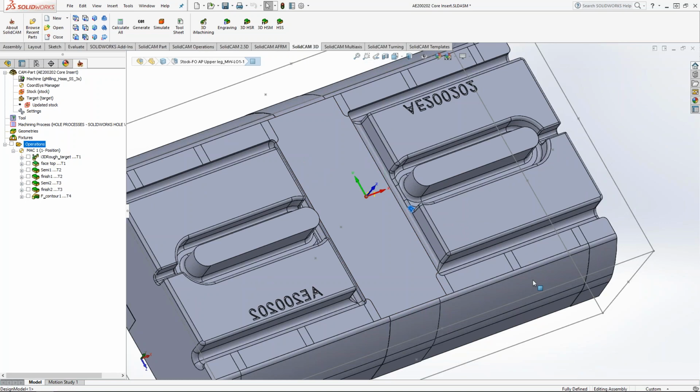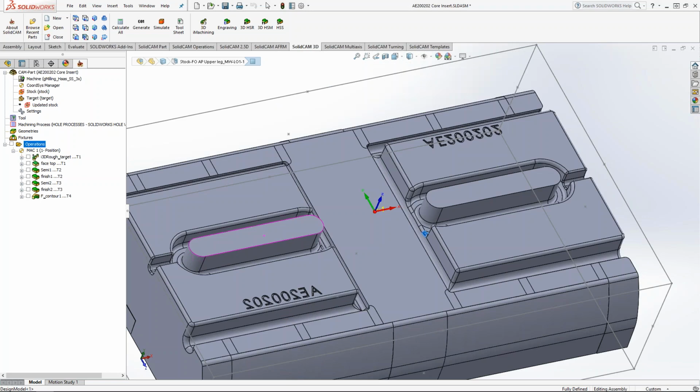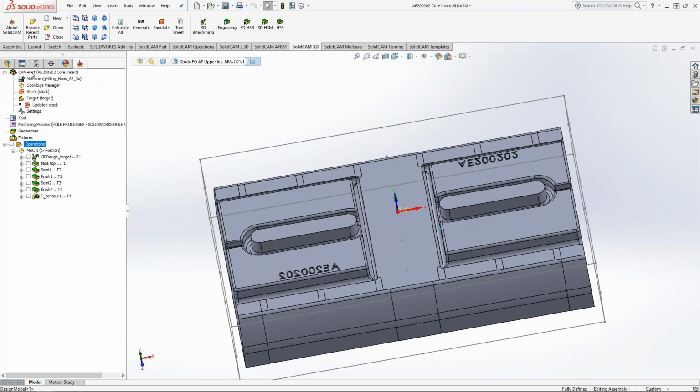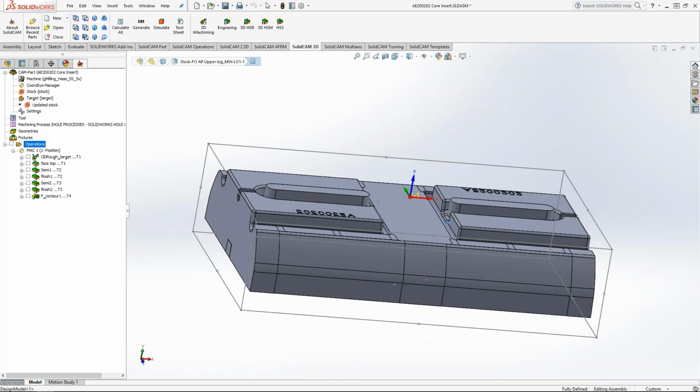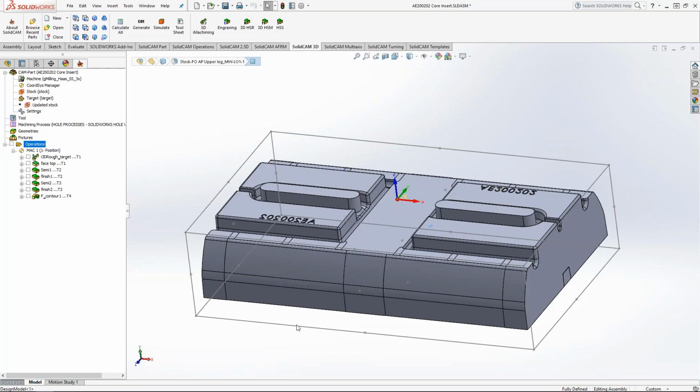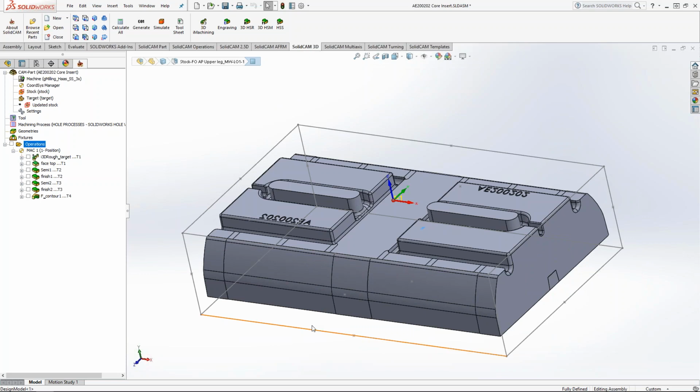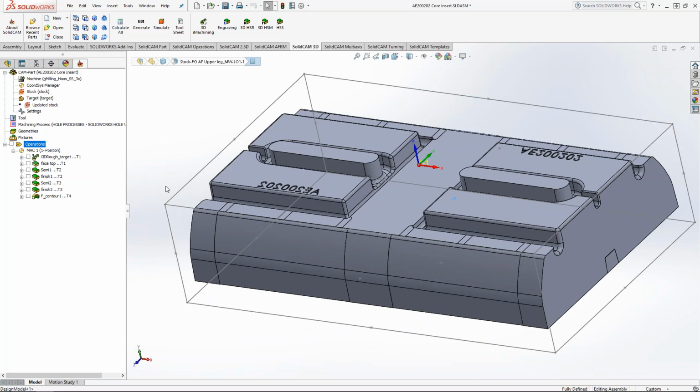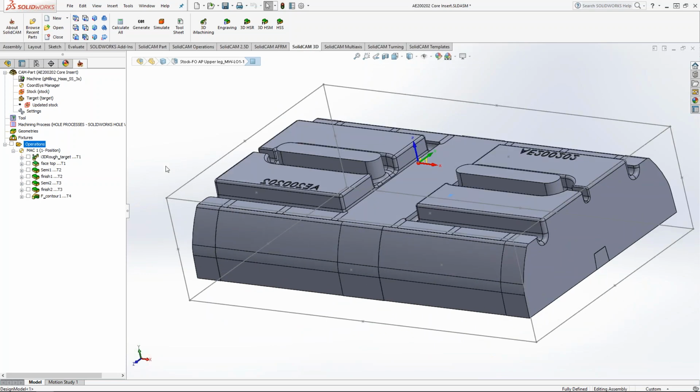And then what are we using for speeds with those cutters, or what material were we cutting here? I think this one was actually aluminum. Oh, was it? Yeah, this was a low volume tool. I want to think we used 7075 aluminum for this one, just because 7075 is a little harder than 6061.